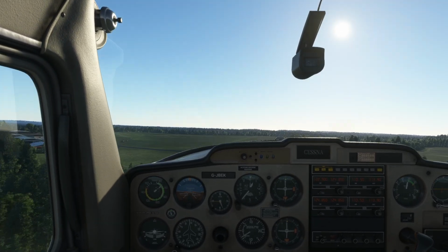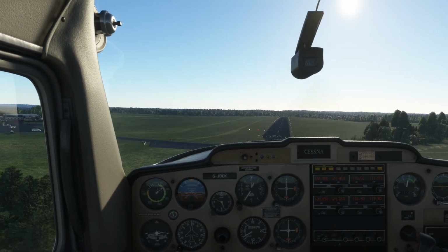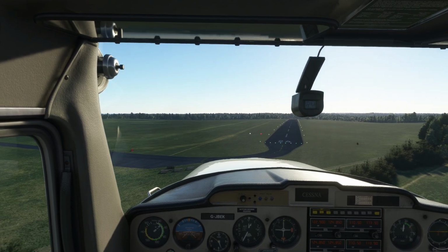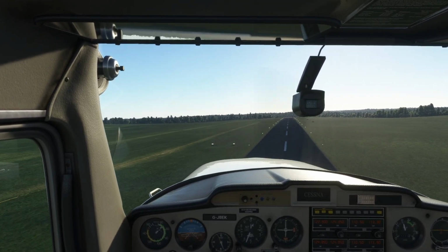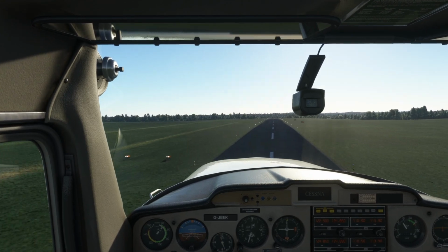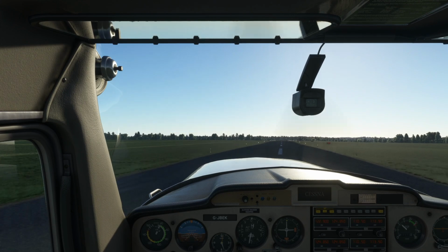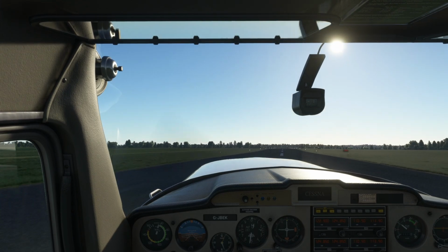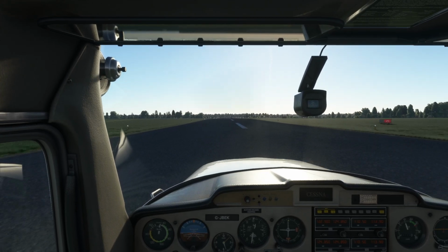There's a lot of turbulence, an awful lot. So I'm going to sit up in the cockpit. So we're crabbing along the centre line, cutting the throttle, and as we fall to the ground, we're going to turn to face the runway with the rudder. Perfect. Okay, let's have one more go at that then.